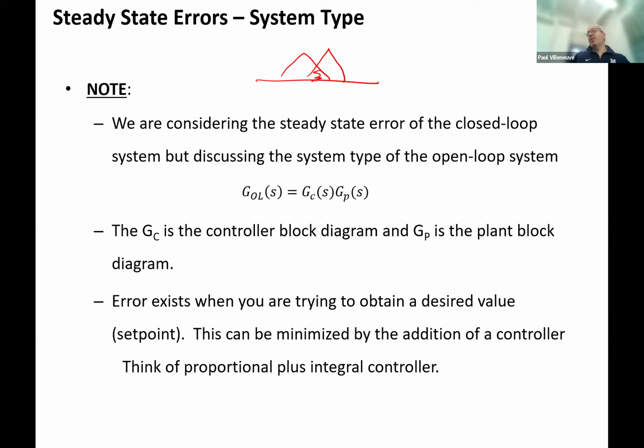If it's a linear system, then why not just go with PID controls? But in more sophisticated controls, you need more nonlinear controls, so you implement that. In the real world, every system is nonlinear, but remember, our friends in the process control industry, their brains hurt enough trying to figure out how to keep these processes running. So what they try to do is linearize the operation of the system. So even today, if you go to any industrial plant, you'll still see PID control. Again, it's just robotics and more sophisticated stuff.